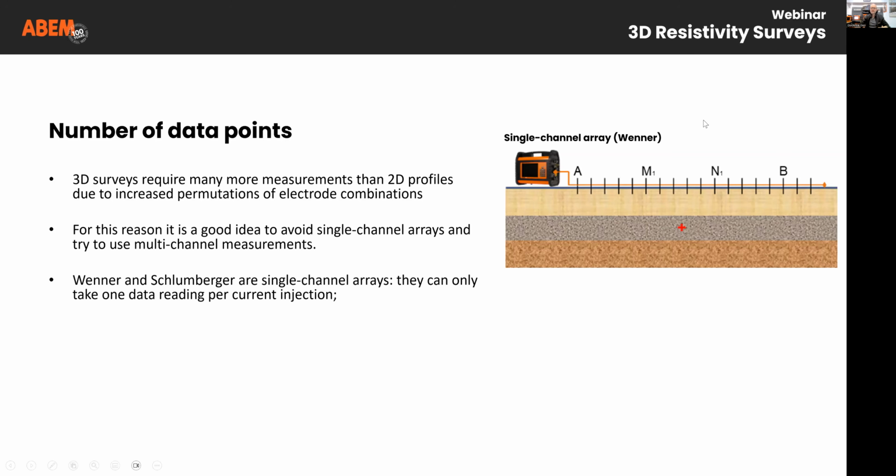That's what defines the Wenner configuration, the Wenner layout. So that means that as soon as I have defined which two electrodes are going to be injecting the current, the two positions where I'll be measuring the voltage are predetermined, because the spacing between all of the electrodes has to be the same. And so therefore, I can't measure voltage in any other position if I want a true Wenner measurement. So for that configuration, when current is being injected between A and B, I have to measure between M and N, which gives me a focus position, the point at which we assume the apparent resistivity has come from. We have that one position.